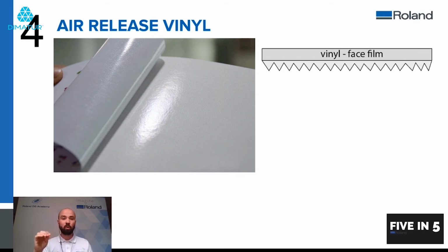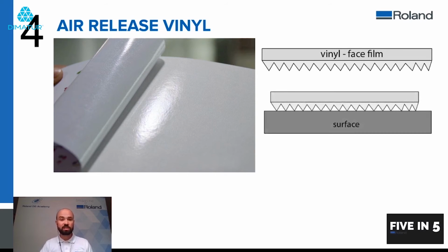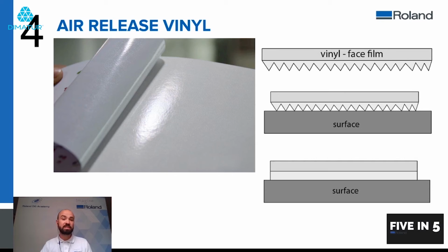So you will have small points which will contact the surface before the others. So when you stick down your material, there will be small channels for the air bubbles that can come from laying down vinyl. These will have somewhere to go when you squeegee them because of these air channels that are created through the adhesive. Once you apply heat or pressure over time, that adhesive will become flat anyway, giving you the same adhesive strength as you would have had with a normal vinyl. However, when you first come to applying these vinyls, it is much easier to do.